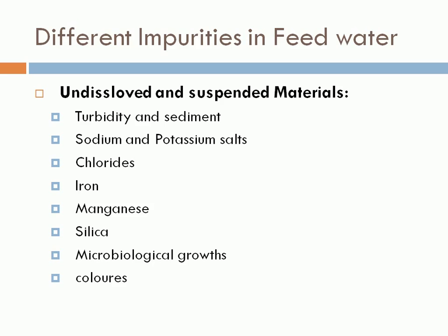This boiler water treatment is used to control the alkalinity, prevent scaling, correct pH, and control the conductivity, so that it does not ruin the tubes. There can be too much conductivity in the feed water when there are too many dissolved solids.